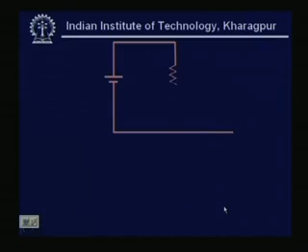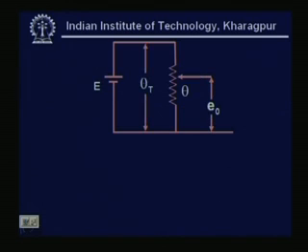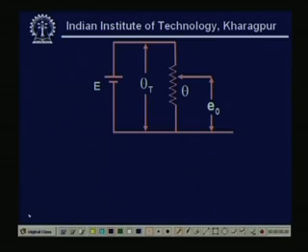Now, I will take an example of a potentiometer. Potentiometer is a very important sensor. You will find it in all electronic circuits, and also in instrumentation it is used as a position sensor, for rotational positions and linear positions. In electronic circuits, potentiometers are extensively used, whether you call it potentiometer, preset or rheostat, all are the same. These are basically potentiometers. A potentiometer is a 3 terminal device, and you can see it here.